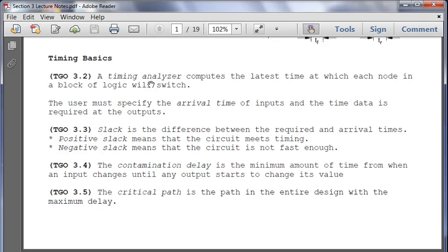So you have A, B, and what are your inputs? What are the 3 inputs to a 1-bit adder? A, B, and then carry in. And then what are your 2 outputs? Sum and carry out. Okay, so that means in order to start the next 1-bit adder, what do I need to do? Yeah, you put carry out into carry in. So your critical path is going to be your 32 carries. So that's the number you're alluding to.